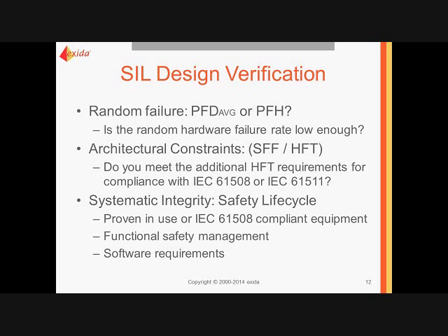From architectural constraints point of view, you're looking at either safe failure fraction or hardware fault tolerance. That's SFF and HFT. So do you meet the additional hardware fault tolerance requirements for compliance with 61508 or 61511 for the particular SIL that you're looking for? Systematic integrity, basically that's looking from the life cycle point of view, at how well the product has been designed and developed.